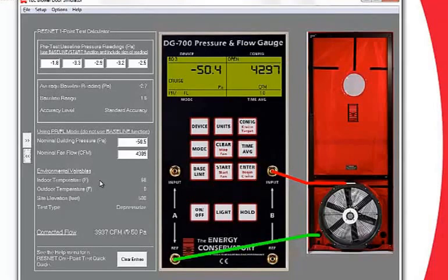And we're actually recommending that people use the RESNET test procedures for code compliance. The 2009 option for a blower door test and the 2012 requirement for a blower door test is actually silent on the actual test standard that you're going to be using. And in lieu of a requirement for it to follow a test standard, our recommendation is to follow the RESNET standard. It's a good, robust test, with good repeatability. And we'd recommend that everybody start using that as their test protocol.